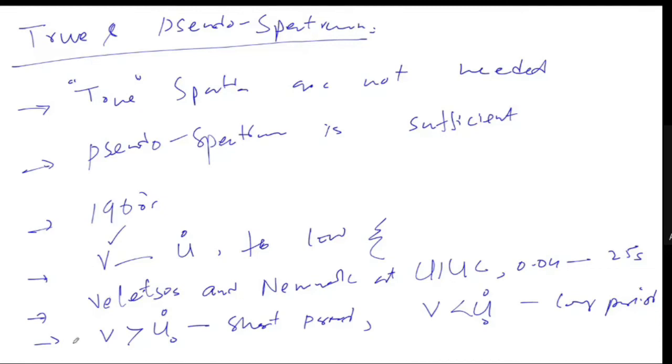Also at that time, work was carried out for the acceleration response spectrum. It was found that the pseudo and the actual total acceleration response spectra were identical for an undamped system.